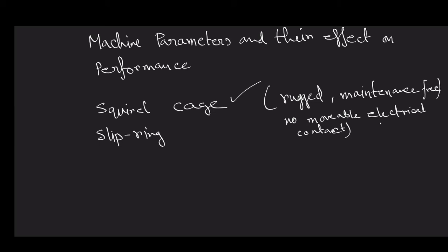In the case of a transformer, the main maintenance cost involves replacing the transformer oil after a certain time, because its electrical property becomes inferior.